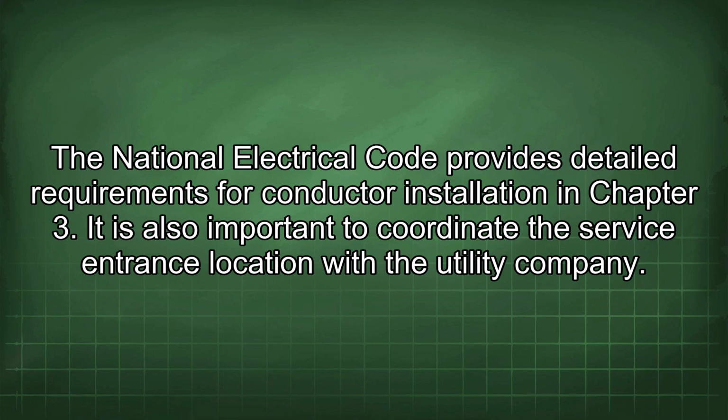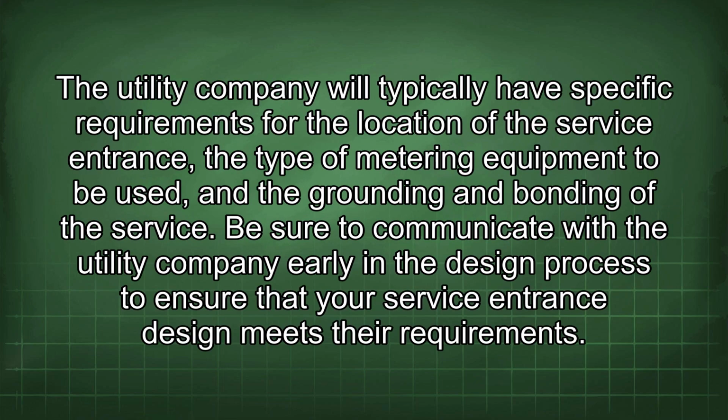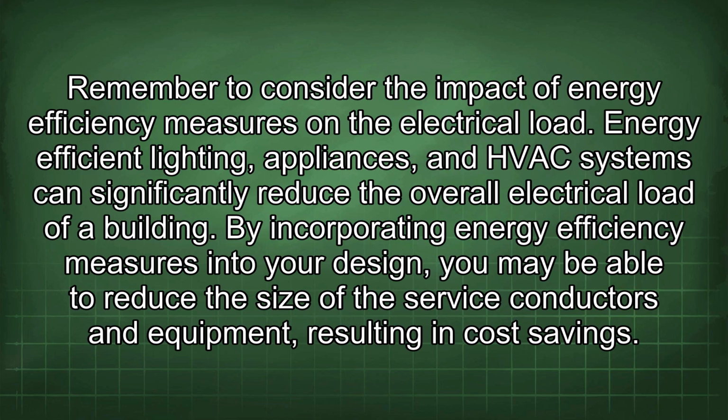It is also important to coordinate the service entrance location with the utility company. The utility company will typically have specific requirements for the location of the service entrance, the type of metering equipment to be used, and the grounding and bonding of the service. Be sure to communicate with the utility company early in the design process to ensure that your service entrance design meets their requirements.